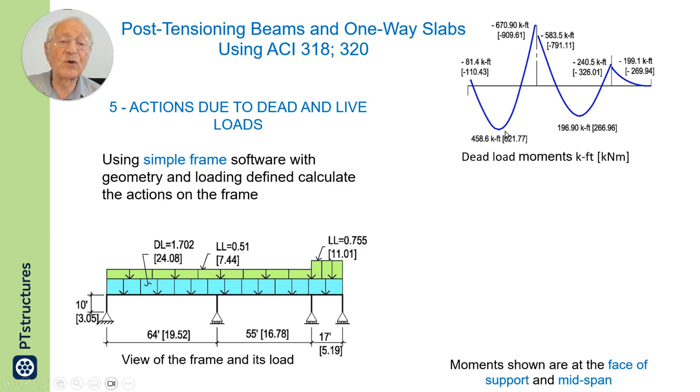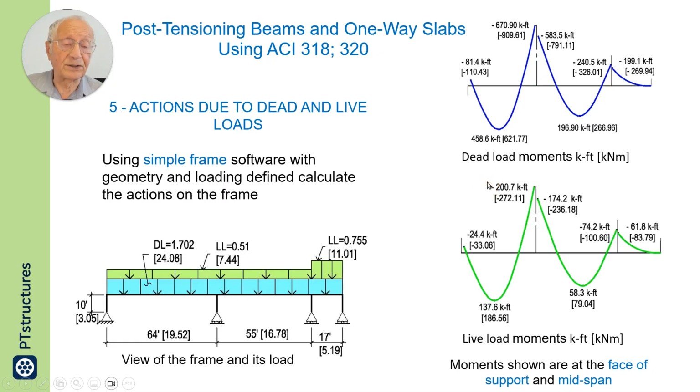The maximum moment is not necessarily at mid-span, but for hand calculation, it is actually common to use the mid-span for code check. If you have a software, the software will most probably calculate the moment maximum where it occurs.